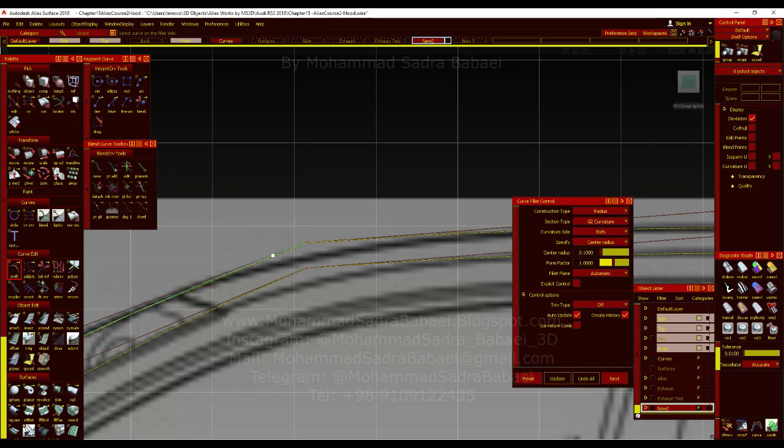Okay, I am adding the fillets manually here to curves, not to surfaces. I'm not going to use the fillet for surfaces, just for the curves, with a curve fillet tool, G1 or G2, anything you want, just create that. Turn on the automatic trim and just try to find a good value.